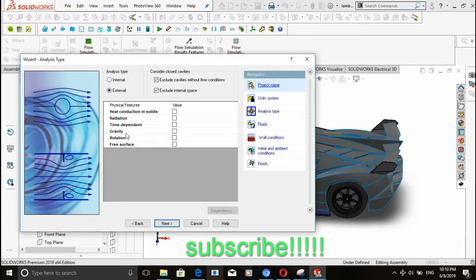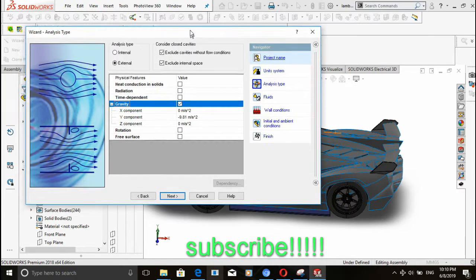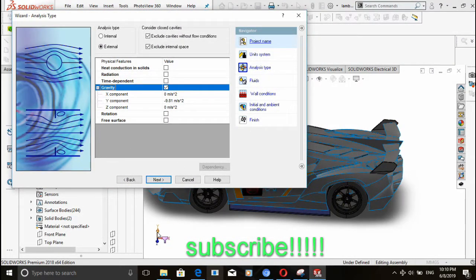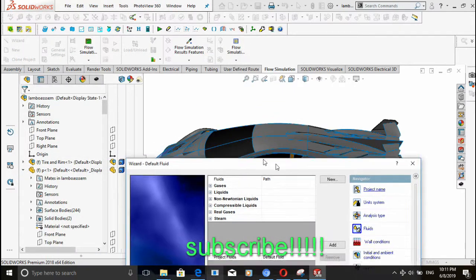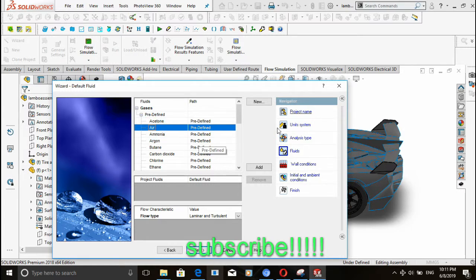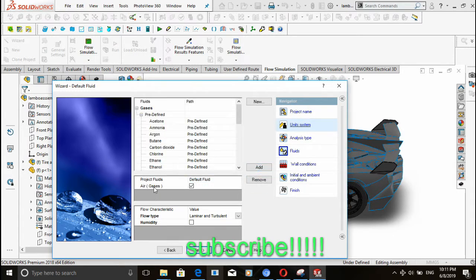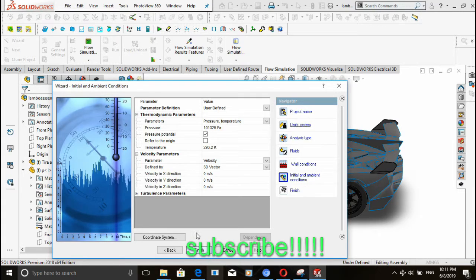Now if you look at this level, you're going to notice that there's gravity. When you check this gravity with respect to the y-axis, that's with respect to our coordinate system, you discover that it's minus 9.81. It's okay. So all these values are okay. I'm just going to continue. Now here we're going to carry out analysis. Here what we have is air, so we want the properties of air to be there. So you're just going to choose gases, air, and hit add. So you choose air as the type of gas. We're going to go next. Here you can set humidity in the air and the flow type that you want. So let's just continue next. We're going to take next.